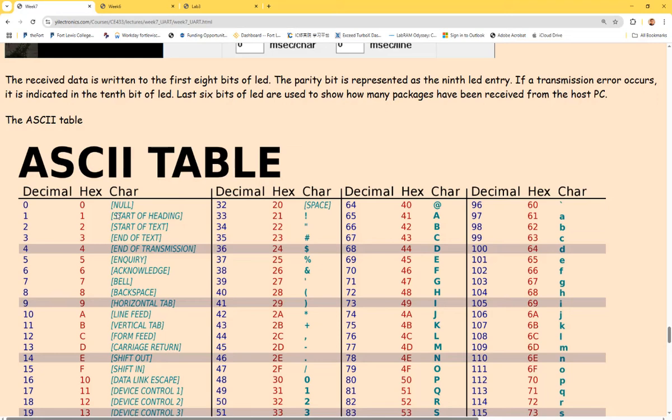So basically, this tutorial shows you how to do a communication from your FPGA to the laptop by pressing a button on the FPGA board. You press it once, it increments starting from 41, which is A, right? You are sending ASCII code from the FPGA to your serial terminal. You can use the Arduino one, you can use a different one, doesn't matter. So you are seeing that displayed in the serial terminal.